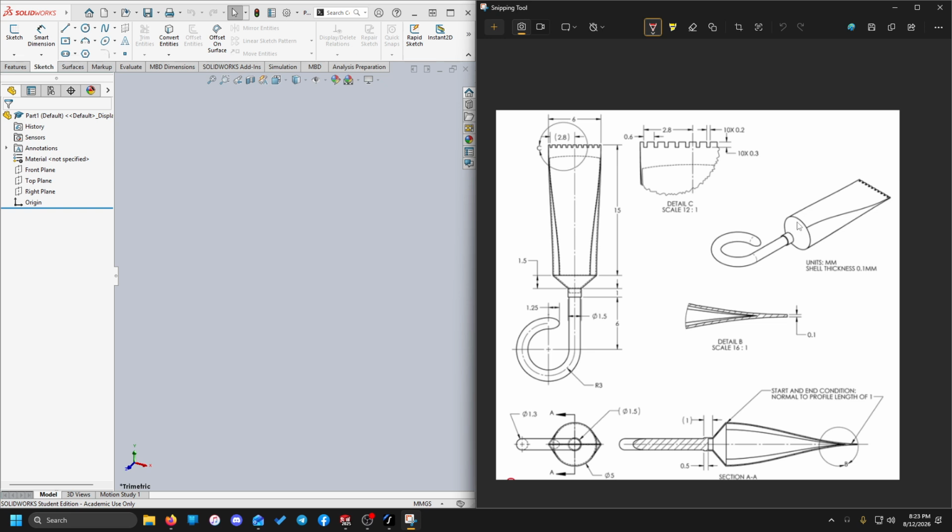So with our loft feature, we see that we've got a circle on one end and a sort of rectangle on the other. So based on our dimensioning, we see that it's 6 units from left to right and 0.1 unit thickness. And then for the circle, our dimension for that is over here, diameter of 5. And then we're probably going to do some kind of revolve to get sort of the conic piece and the cylinder. And then for our curl, we can probably do a sweep to sort of get that down, and then probably a dome or revolve to get the sort of end cap on it there.